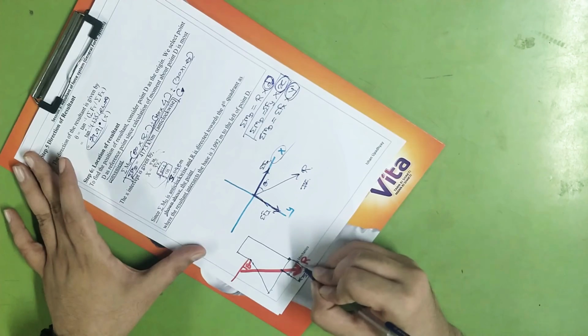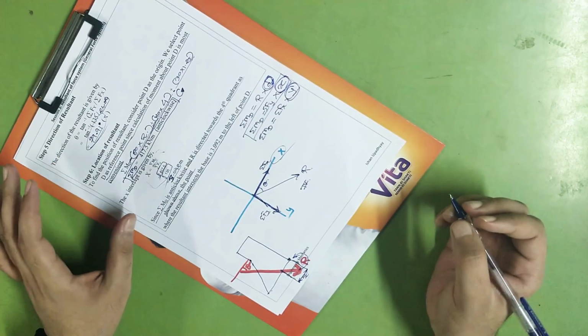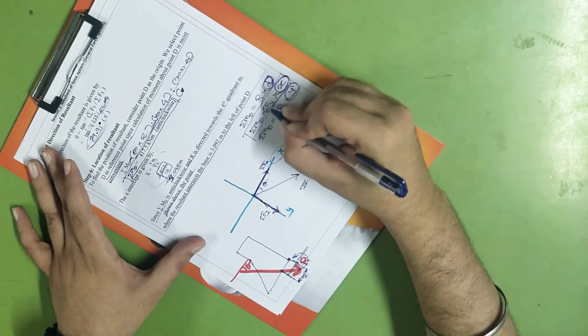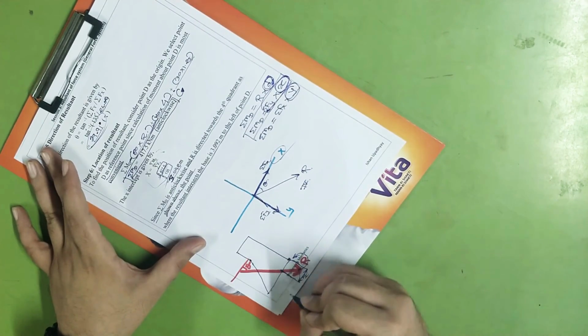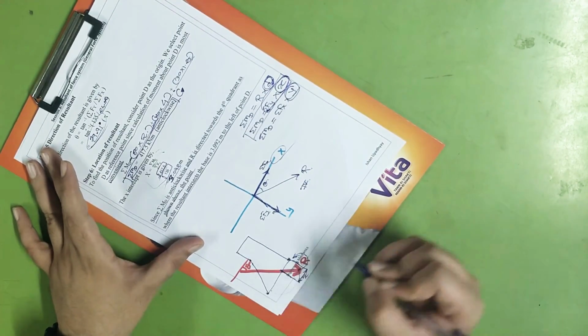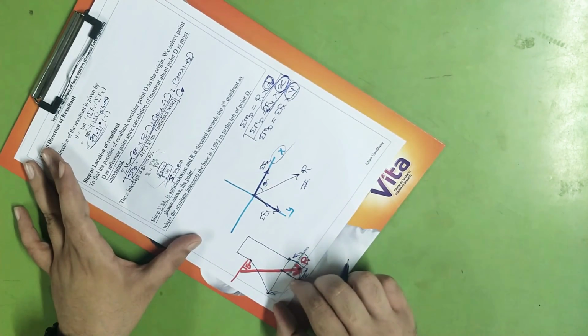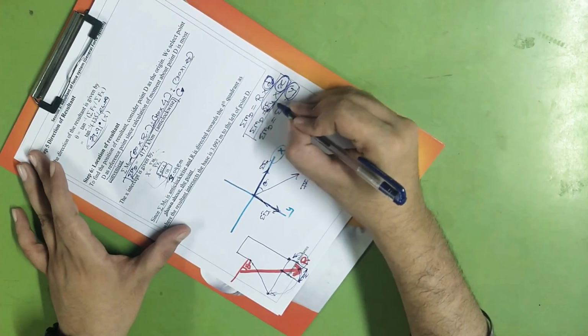what is the moment produced by this R. This R is producing moment in what direction? Anti-clockwise, and that is why here I have considered summation of Fy into x as positive. Suppose here R produced a clockwise moment, then if I had taken moment about O, this R into this, now this time this would become x, so I would have had to take a minus sign, so minus of Fy into x.